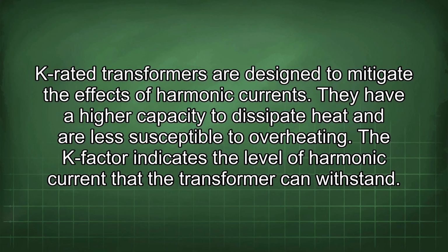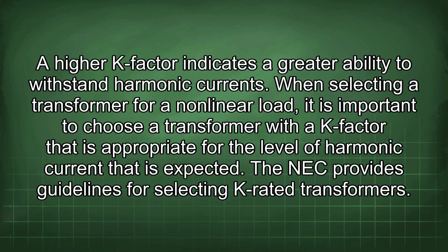They have a higher capacity to dissipate heat and are less susceptible to overheating. The K-factor indicates the level of harmonic current that the transformer can withstand. A higher K-factor indicates a greater ability to withstand harmonic currents. When selecting a transformer for a nonlinear load, it is important to choose a transformer with a K-factor that is appropriate for the level of harmonic current that is expected. The NEC provides guidelines for selecting K-rated transformers.